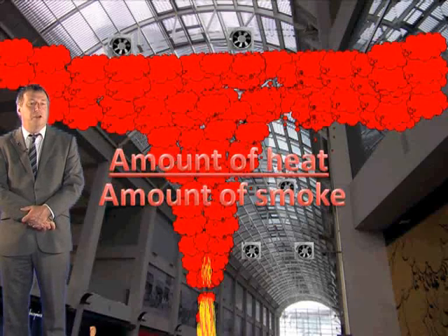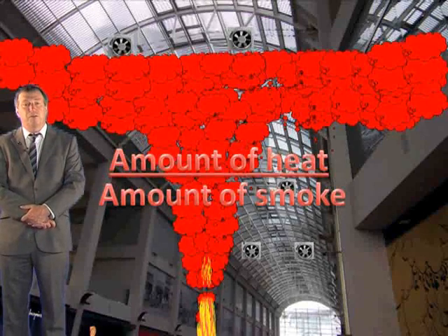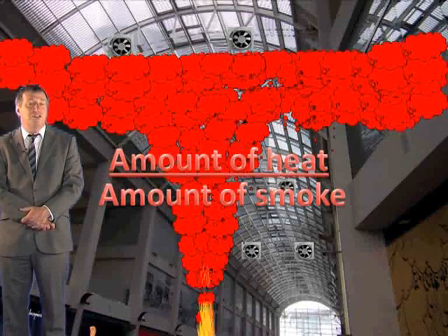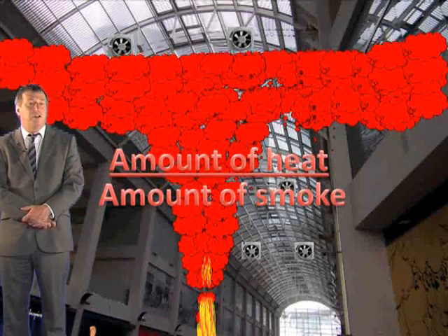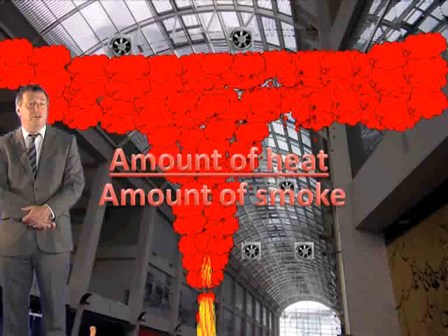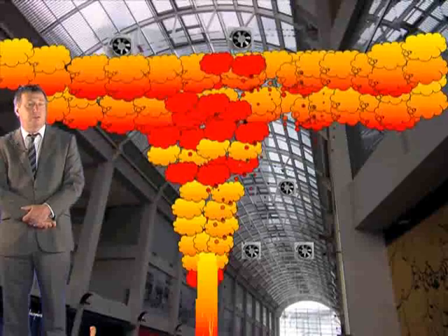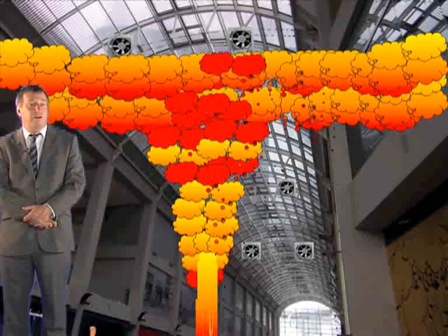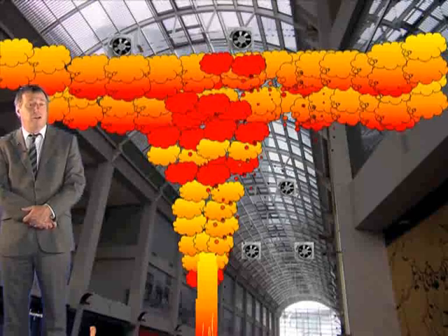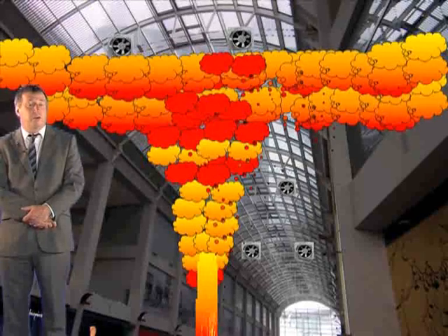Let's look at what we've done in these examples. In effect, we've divided the total heat that is contained in the smoke by the amount of smoke to give us a representation of how densely the heat is distributed within the smoke. This representation is converted by the application of the specific heat of air to a temperature rise above ambient, which is theta. The more smoke that is produced, the more thinly the heat within the smoke will be spread out, and so the cooler the smoke will be. For smaller amounts of smoke, the heat is less spread out and is more concentrated, and so we have a hotter mean temperature rise for the smoke layer.